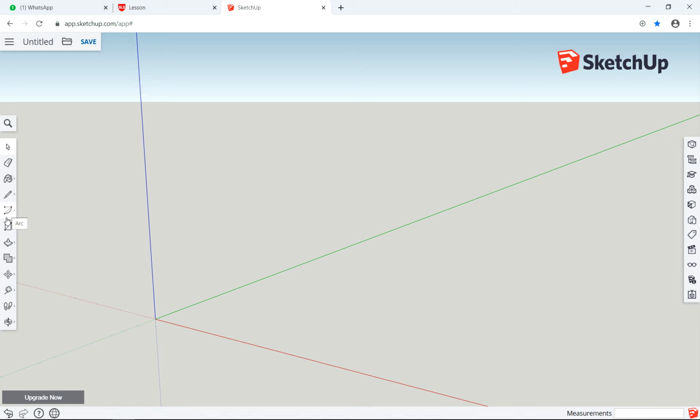So you need a while to get used to it. This is to draw rectangle. So I need to create a base first, so I select rectangle, I pull it out. Okay, you see the dimensions at the side, they are all in mm. So like in the software also, what you need to do is to make sure that everything is used the correct way, so you enter the dimensions, so it will be 300 by 250, enter. Okay, very small, can't see, so you need to use the zoom function. So this is the display, model info, solid inspectors, views.